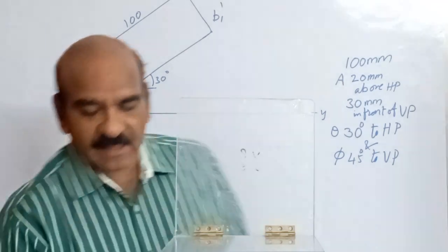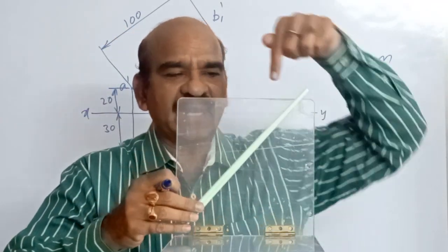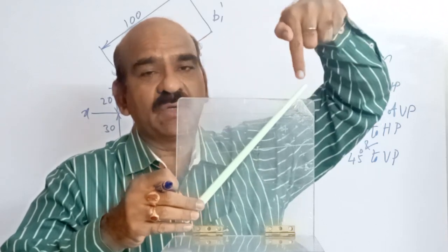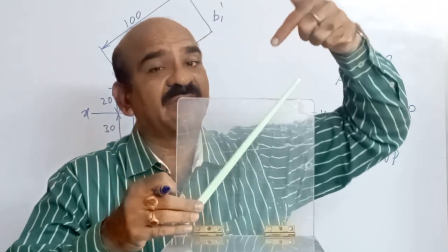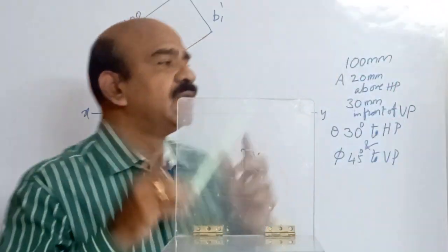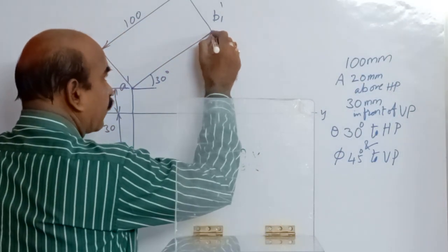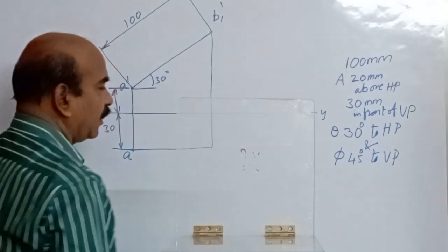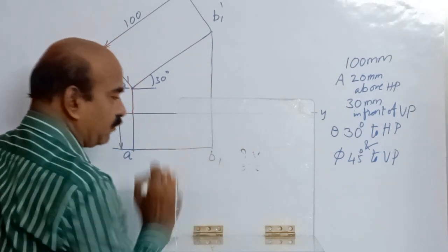When you see this line in the top view, we see the projection on the horizontal plane parallel to the reference line and in front of it, 30 mm in front of it. So here it is, draw projectors, 30 mm, right? I call this B1.